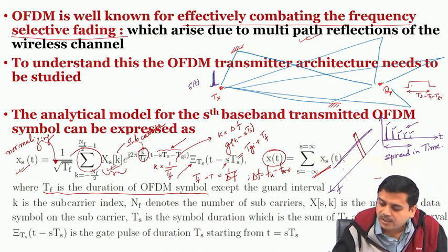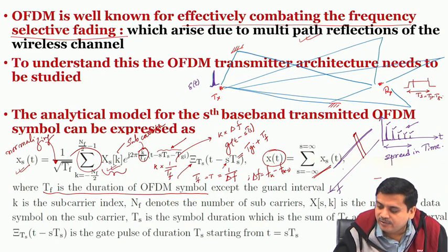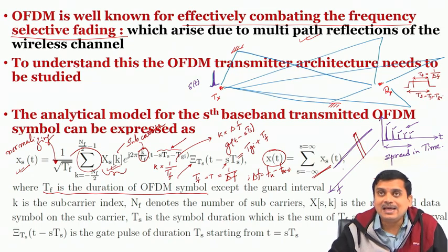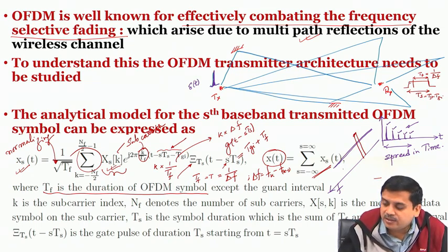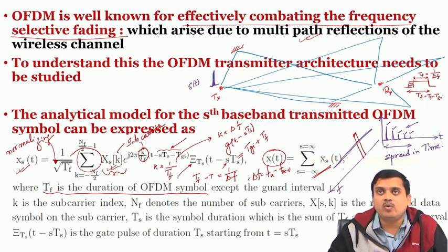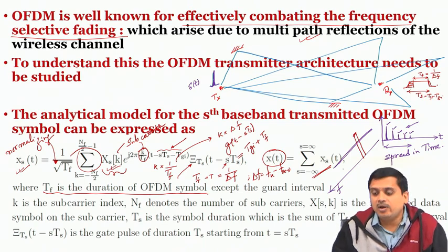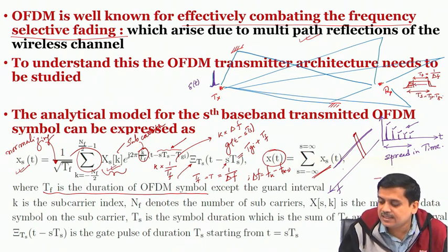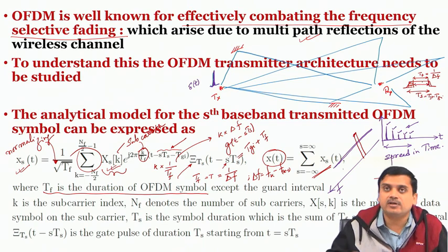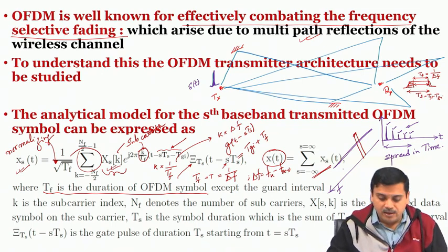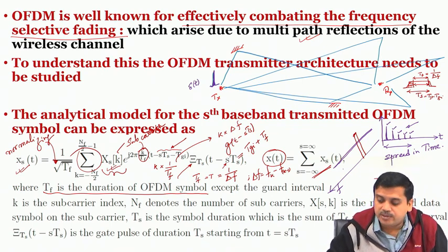So, that means if we say that this duration is the duration of Tf, okay, which is equal to 1 upon delta f, right, Ts is actually larger than that, and the extra portion is the cyclic prefix. Now one can easily see that we can have some shaping over here and some shaping at the end without affecting the rectangularness within the region of our consideration. Okay. All right. So, we will discuss again some more things there.